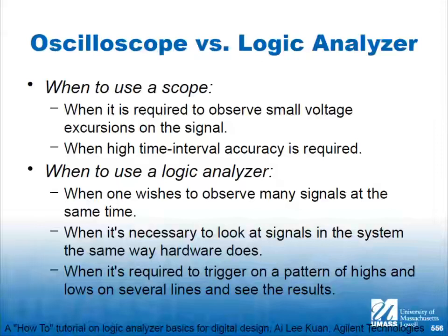So, reasonably, if we're not too close to the top and bottom, we can get 200 samples from the lowest to the highest of a transition signal. But that's not what we want to see. We just want to know when it's low and when it's high. But we want to see a lot of them. So that's what a logic analyzer does.